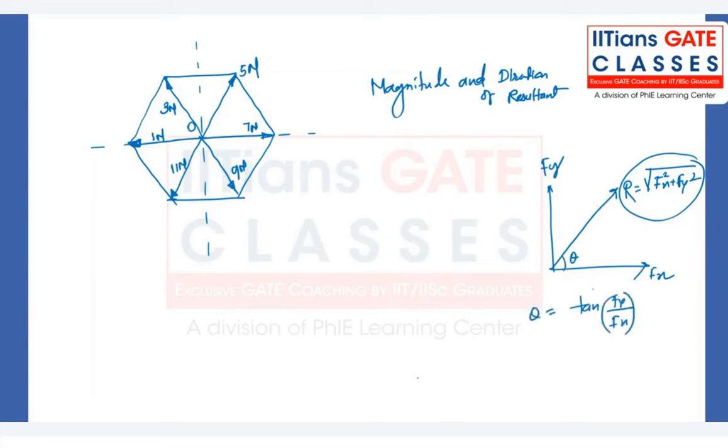It will give you the angle at which this resultant is there with respect to the horizontal. This same law you have to apply here, but now you are not dealing with single forces in x and y. You got multiple forces randomly distributed, so every force will have some x component and some y component. You will have the total of forces in the x direction and y direction, their summation, and then you have to deal with the resultant.